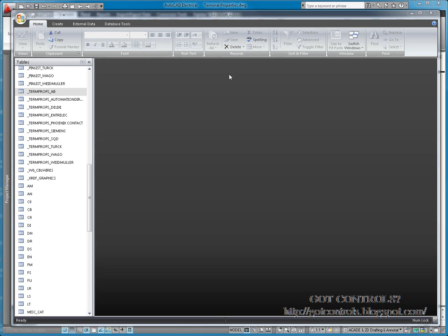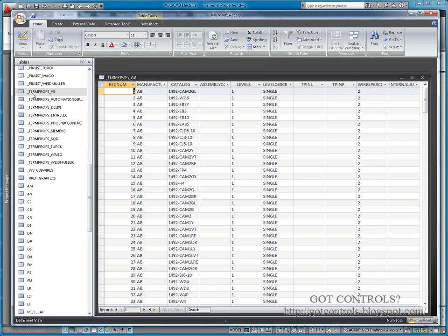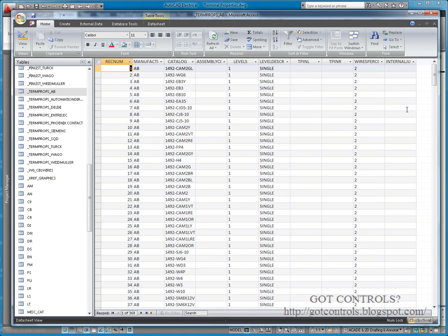This is very similar to the pin list that you've been working with in AutoCAD Electrical for years, if you've been working with AutoCAD Electrical for that long. It's all based upon catalog numbers. So you'll see I can assign properties on the fly to these terminals, or when I select the part number, it looks for an entry in these term props tables to see if there's any terminal properties to pull across with the part number when it's selected. So it can happen automatically for you as well.